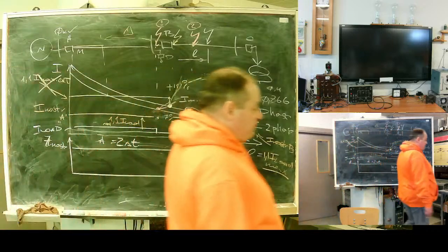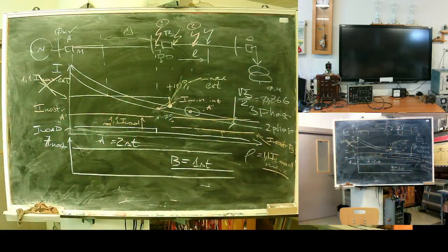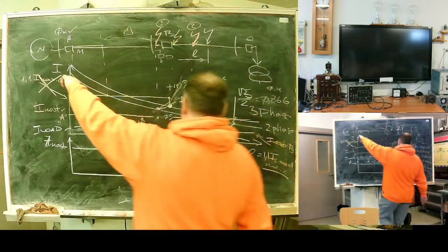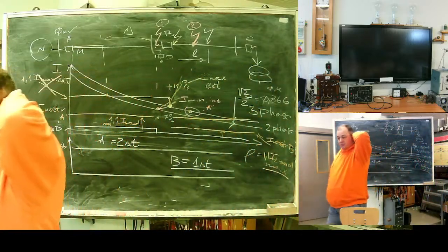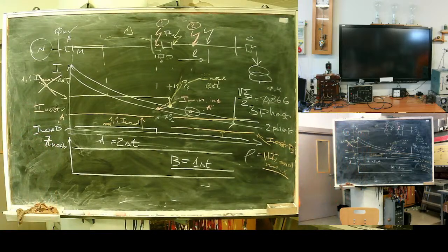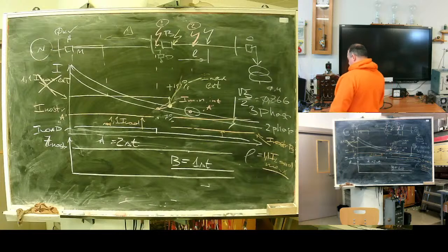The idea is to have the time delay decreasing from the center of supply. Time delay should decrease this way, from the center of supply, to make the tail protections operate first. Understood?